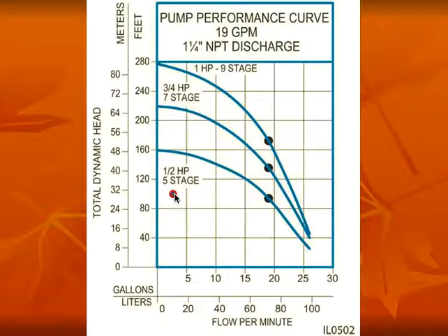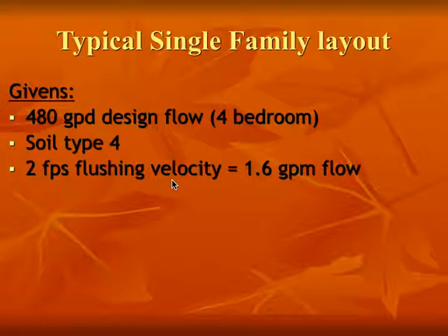Now that minimum flow rate of about 3.74 is roughly here on our chart. Again, this is flow on the bottom, and that was going to be at 104 feet of head. So you can see at this operating point, we are well under the curve, and so our constant pump selection will work with this particular application. But there's more head requirement for the system. We'll go through and give an example of what we mean here.